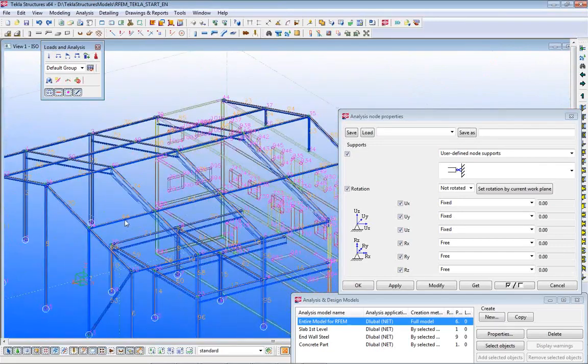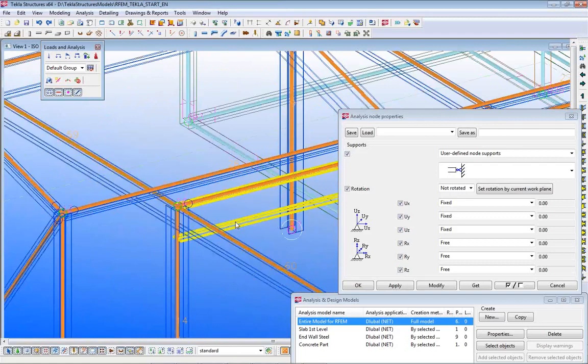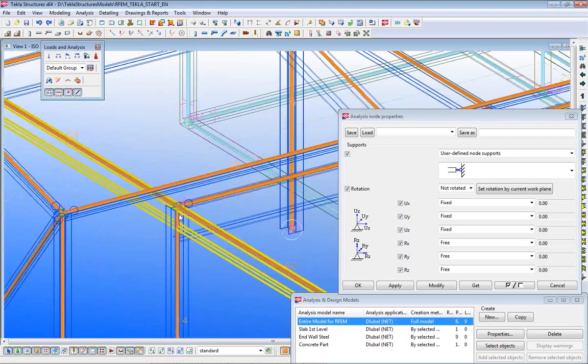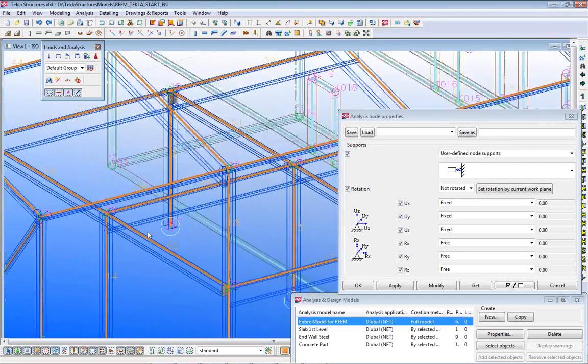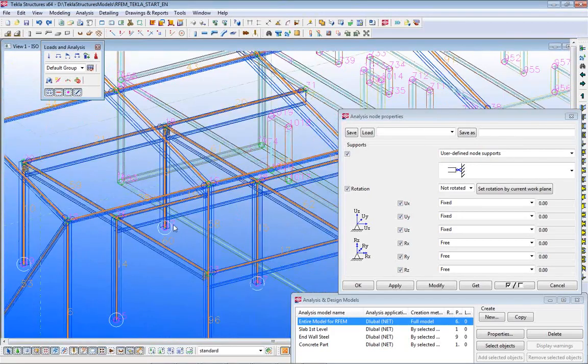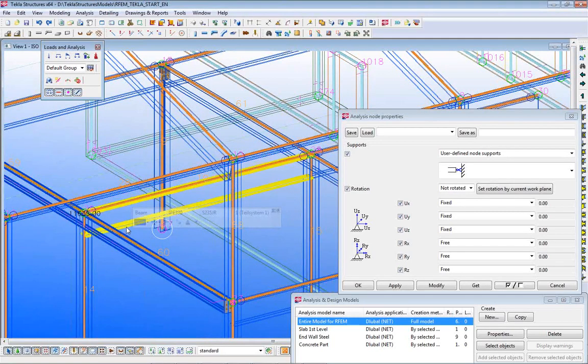I've made the model in such a way, for example, that those beams here are modeled as top of steel, and this analytical model lies on top of the, in the center of the top flange. So it's one level. And important is when we update the sections later, that those sections, even if they change in the section, they should stay top of steel.